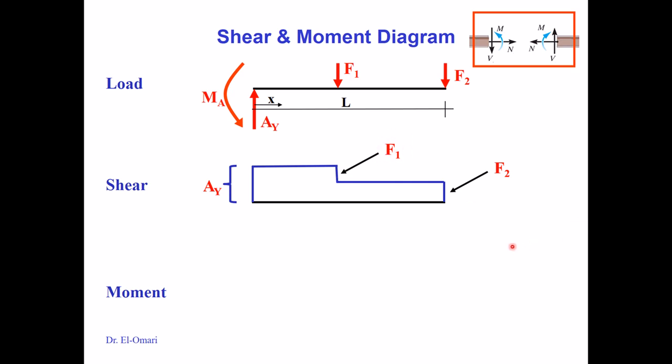So how do we draw a moment diagram? I'm doing that without any magnitudes, but just to give you some important tips about drawing the diagrams. You see in the moment diagrams, the only drops you see are wherever you have a couple moment or free moment like that.